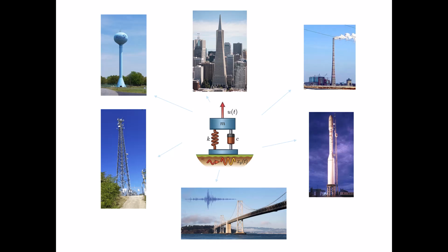We're going to have a lot of fun modeling structures. We are going to get into structural dynamics and the generalized eigenvalue problem, and all sorts of fun things, modal response spectrum analysis, and so forth. So in the center, we've got this spring mass system. It's a single degree of freedom system. We've got a mass M and a dashpot C. Hooke's law gives us a stiffness K. Then we've got this ground motion, and then the response of the mass.